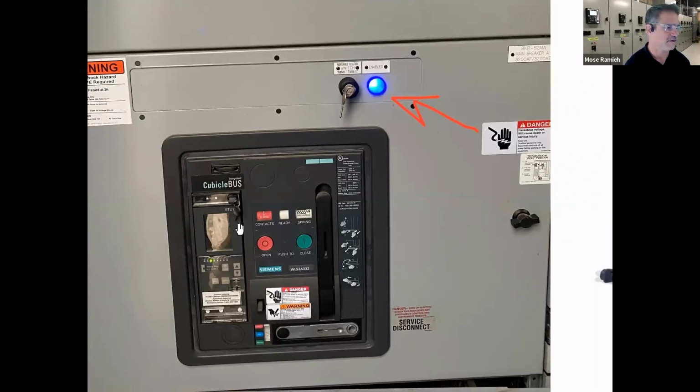What that does is it's a set of contacts that tells the trip unit to use an alternate set of settings. So basically it lowers settings, in particular the instantaneous, which you might have set at 7 or 8 times. It will lower it down to 1.5 or 2 or whatever it's set for. And by doing that, if somebody's working downstream of this breaker, doing switching, taking a voltage reading, if something were to go wrong, the arc flash hazard will be greatly reduced using the maintenance mode, right?